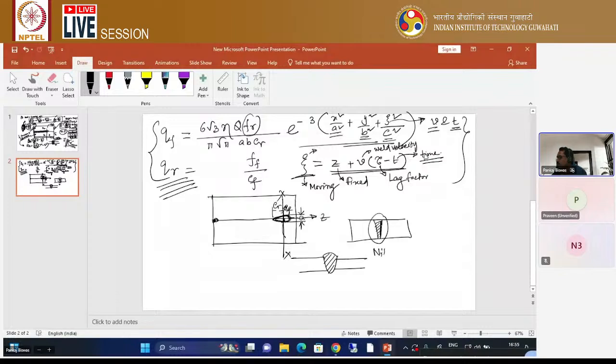Can you recall nital solution? Yes, sir. I have already told you. First of all you need to cut the section in any weld region. Once you cut it, you will see your weld bead cross section, which looks like this. There is a top bead, you can say that top bead is called top reinforcement, and this